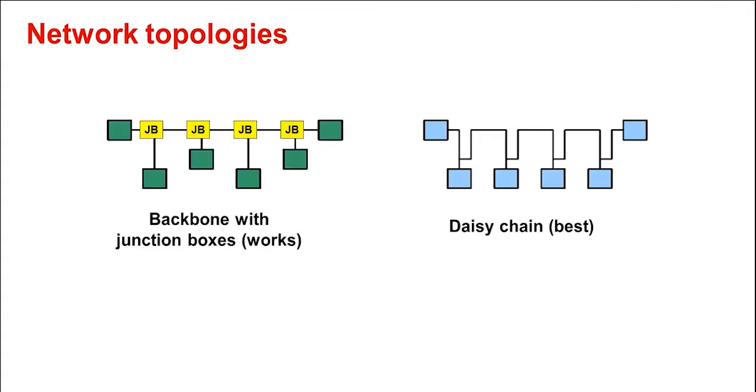The RS-485 standard suggests that the nodes be networked in a daisy chain. In this topology, the participating drivers, receivers, and transceivers connect to a main cable trunk via short network stubs. The interface bus can be designed for full duplex or half duplex transmission. An alternative to the daisy chain topology is the junction box approach. This should be implemented in a way to minimize stub lengths and thus reduce reflections. If a non-ideal network topology must be used, it is best to insert a repeater node at each junction.